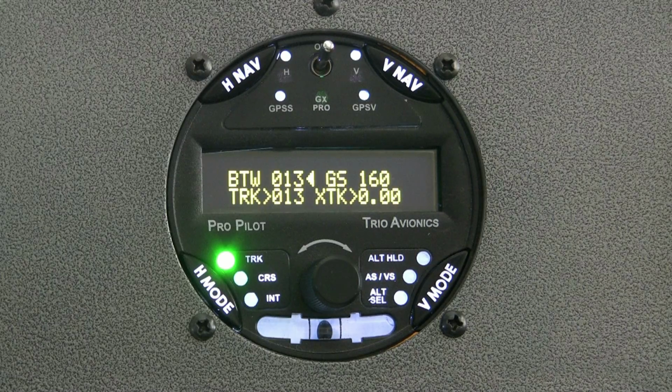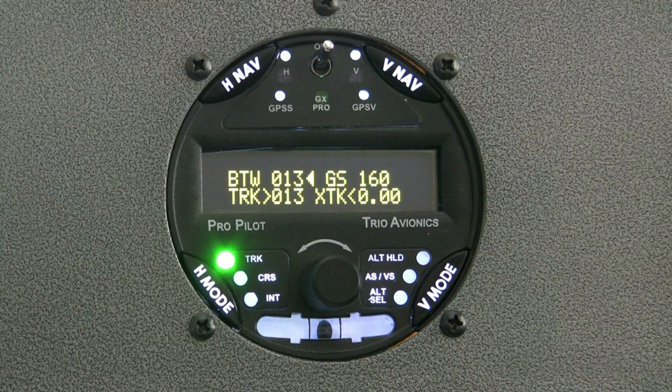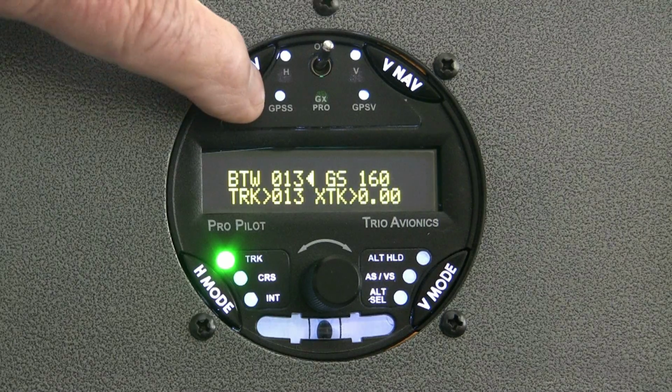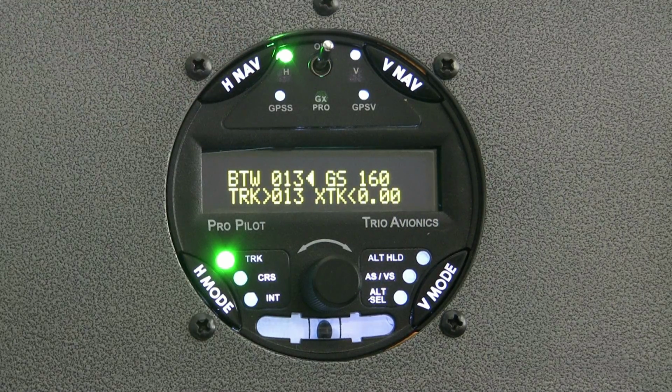With a proper GPS flight plan entered into the GPS receiver, it's a simple matter to engage the system to control the ailerons of the aircraft. In flight, once clear of the airport traffic area, the pilot initiates autopilot control of the ailerons by pressing the H-nav button. This activates the aileron servo. The ProPilot will then fly the aircraft to the flight plan course line and remain tightly on that line during the flight.